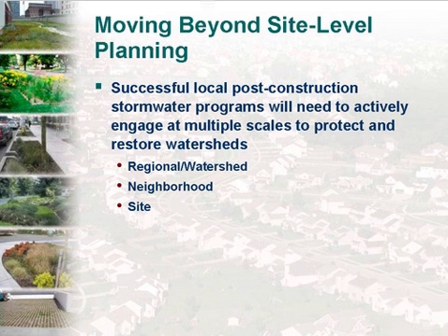Good. So now moving on to our next section here. Today we're talking a lot, and in a minute we'll be talking even more, about site-level decisions. A lot of the stormwater program is focused on site-level impacts, whether we're developing a new residential development, or a particular parking lot that we might want to retrofit. We have a lot of focus on this site level. One thing I want to remind everybody, and we'll be talking more about this in the post-construction manual, is that in the stormwater program, we really need to take our view up as well. We need to start thinking at larger scales, at the neighborhood scale, the watershed scale, or regional scale, whatever terms you like, and thinking about how BMPs are performing at a bigger scale than just one site at a time.